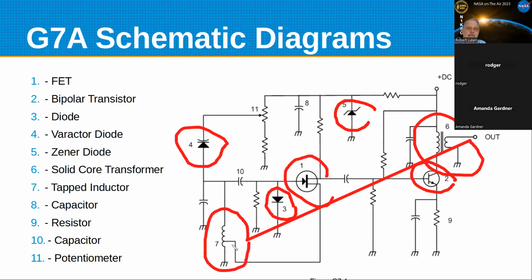So in this case, it would be a step-up auto transformer as far as this point right there. Matching transformers will normally be configured as an auto transformer as opposed to two separate windings.